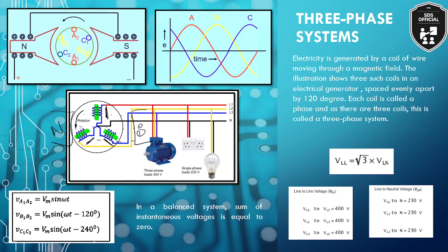So as these three windings are placed 120 degree mechanically apart, they will observe the production of induced EMF in all three windings, which will be 120 degree apart electrically. So the graph of the induced EMF in these three windings would be like this. Let us say in the A winding, it is represented by the color red. In the B winding, the same EMF will be produced, but it will be displaced by an angle of 120 degree.